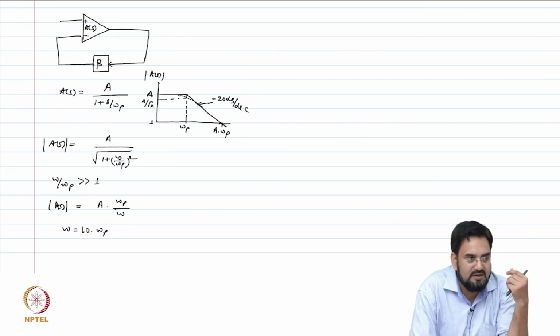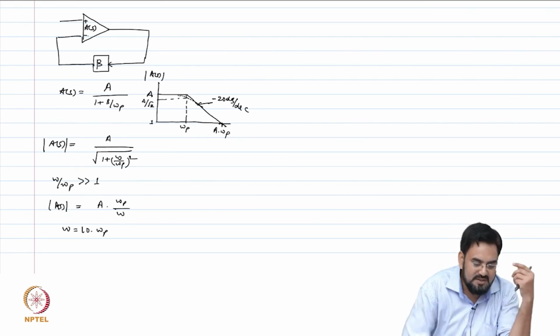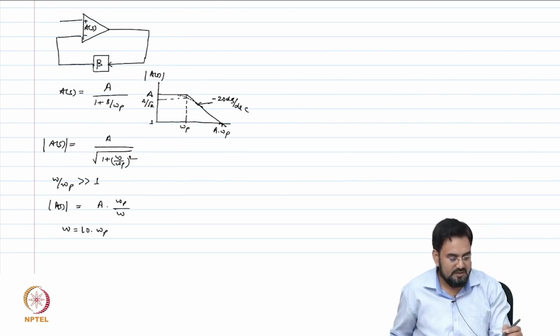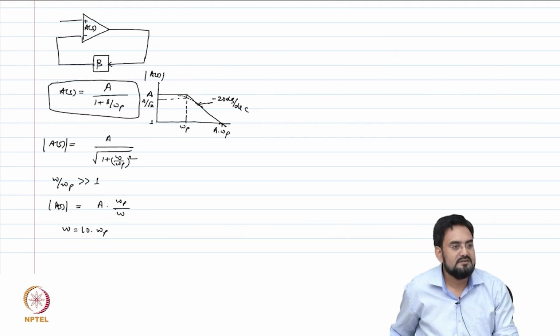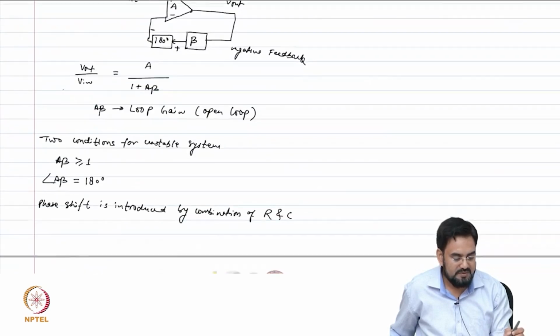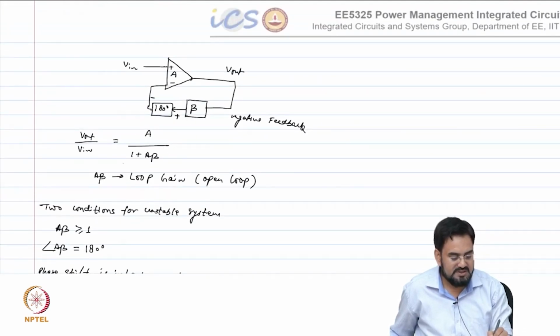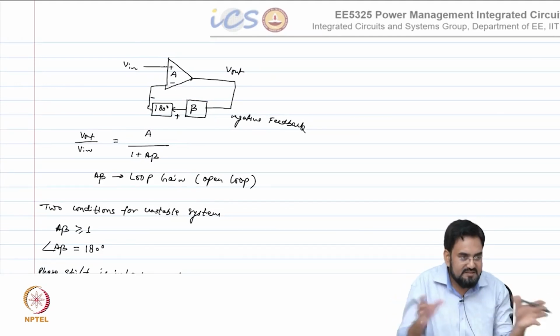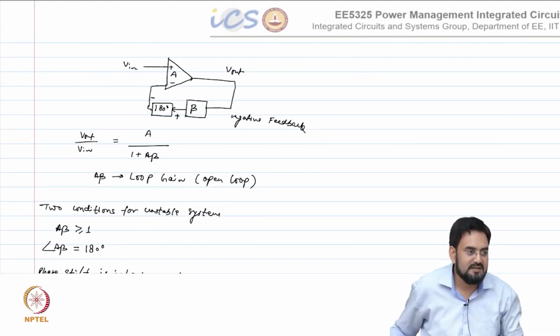And think about, you have a second order system, you put in the closed loop system. Let's say beta equal to 1. If beta equal to 1, then this becomes your loop gain, correct? Now in the closed loop, you have to substitute that A(s) here, you have to expand this. So your equation will become a little bit complicated here.